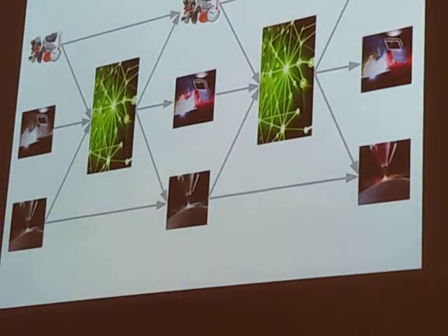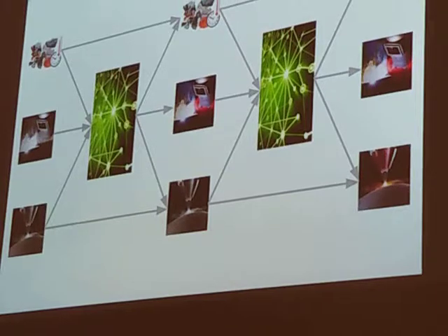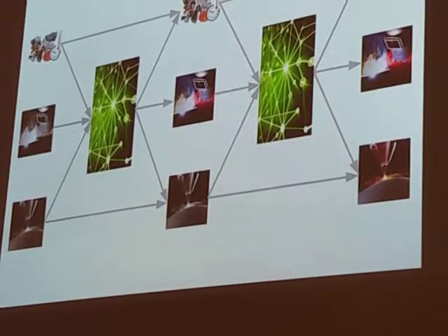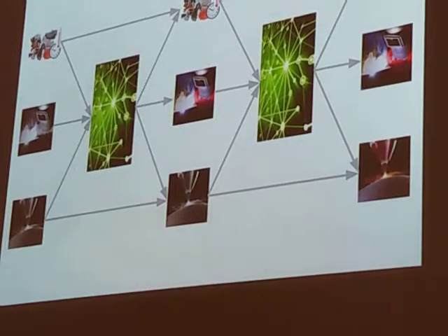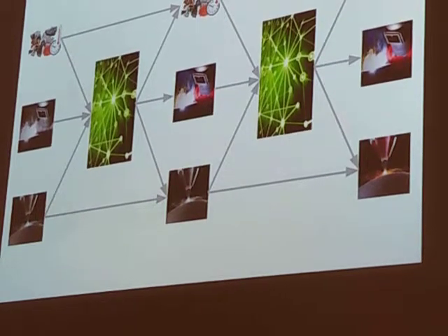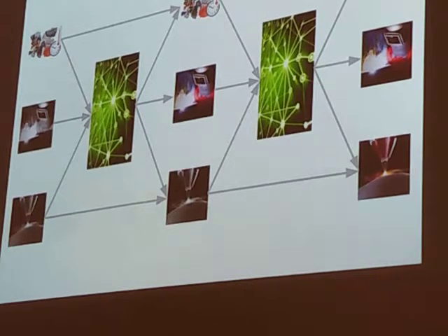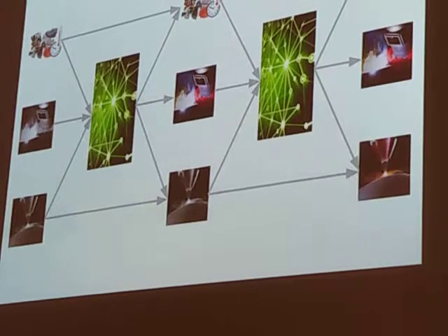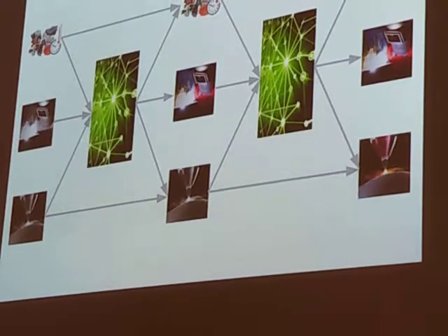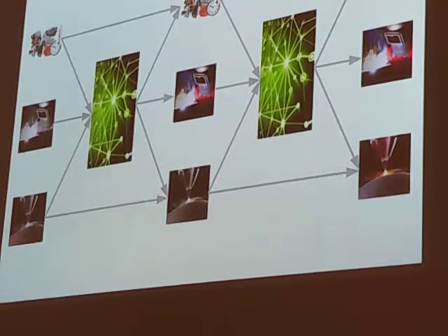Now that we have the weldability, it can pass down and predict for us what the processability is. And so one can set up a neural network just like this. It's got several layers in which you recursively go through and refine your suggestions until you're able to get good predictions for all of those output values, and then we're truly able to use the information of the weldability to help infer for us what that very difficult to predict processability is.